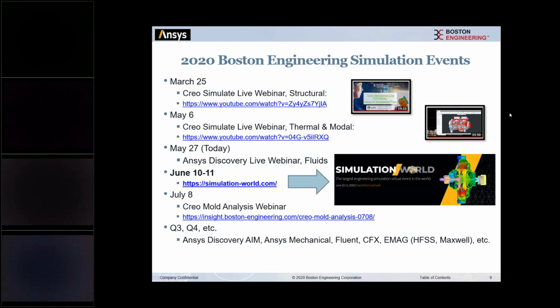It's going to be a matter of whether the Ansys Cloud is going to provide any value that we can't already get locally, right? Because anytime we talk about sending something remotely, there's going to be additional overhead. Who knows, it could be a few seconds, but right now with some of the larger models, we do have bandwidth issues on large stuff for the CPU-based tools, which is one of the reasons why Ansys Discovery Live was developed straight up with the GPU, so that we can keep it local, keep it fast. Great question.